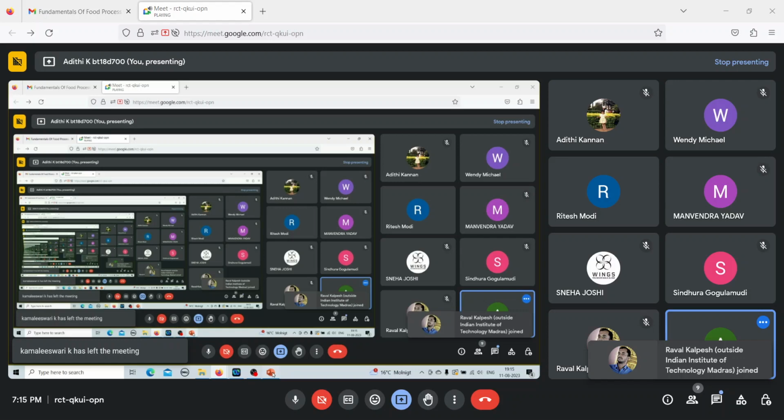Plus, for the second data point, 25 minutes into 10 power 95 degrees Celsius minus 121 degrees Celsius divided by 10, plus for the third data point, 20 minutes into 10 power 105 degrees Celsius minus 121 degrees Celsius divided by 10. So now when you sum up, the F naught is equal to 0.565 minutes. So this was asked 2 years back, that is in 2021.